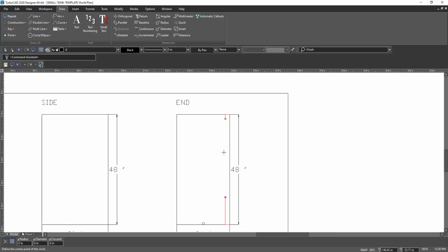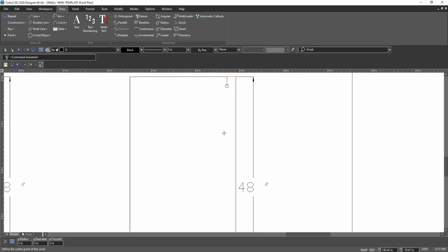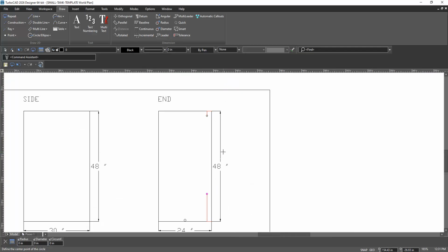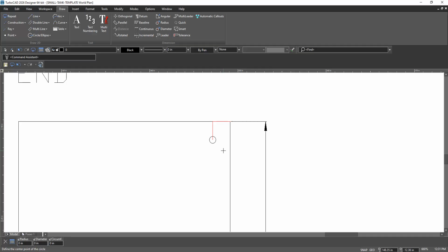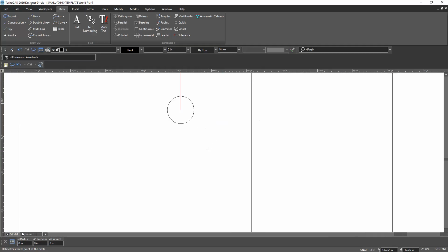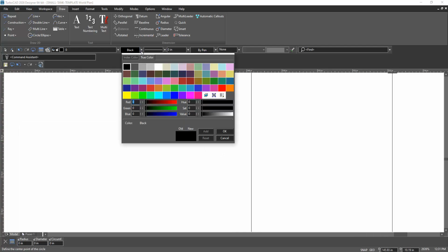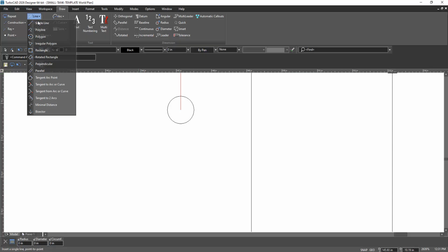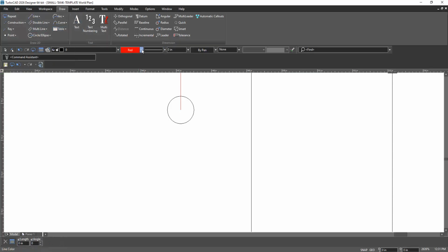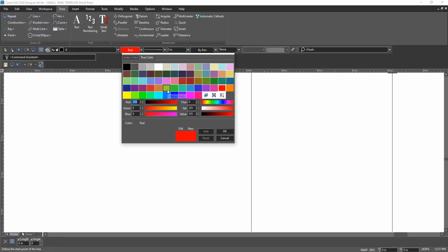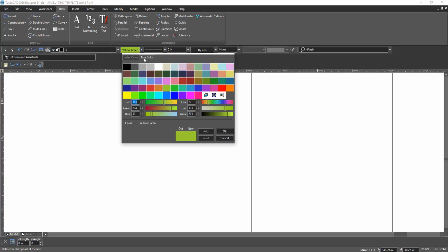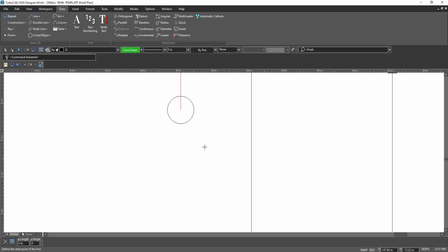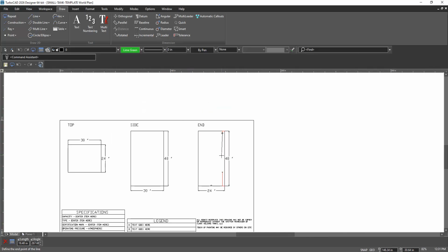Now, halfway in between the center of these two circles, we want to do another one. It's going to be right in the middle. So you want to start with another temporary line, and you want to start it. We're going to make this line, let's do line, single line. Let's make this line green, just so we can differentiate, okay? So you can select any green color, it doesn't matter, any green color on here. Want to start at the end of the red line.